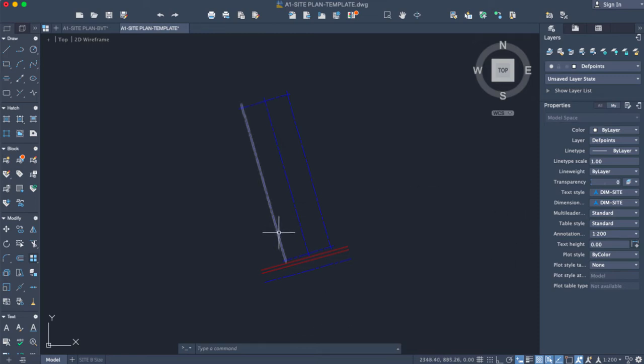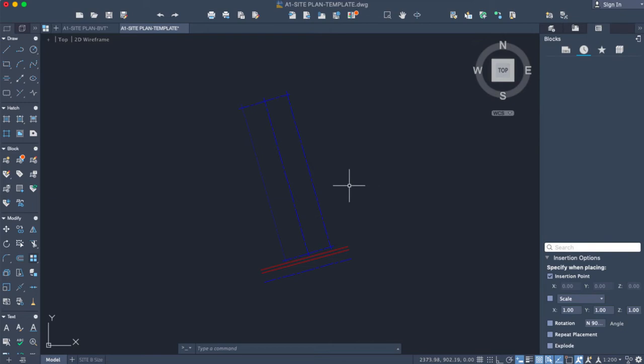The next thing, you will be inserting those points, the elevation grade points, for all the property lines that it's showing on the drawing. So again, by typing I and Enter, make sure you're inserting the elevation PT. That's the elevation point mark that I give you as a block, so you don't have to create it. You will be inserting it, and then we can place it later to the correct place.